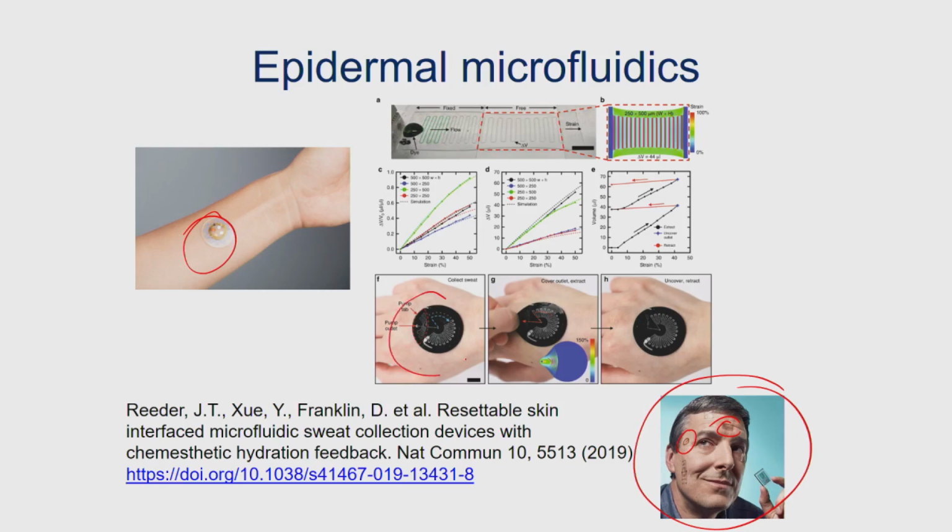And then this is another epidermal microfluidic device which also has a pump. You have the pumps designed on top, more like a pressure pump. You just apply thumb pressure and push the device so that it gets distributed into these channels. So you have your sweat collected here, you apply the pump which is designed on top of this polymeric layer, with a pump inlet and pump outlet. You apply pressure and it pushes everything inwards towards these radial channels, and you can see it starts to fill up all the different channels, and you have the biosensors underneath the channels which can do multi-analyte sensing as well.